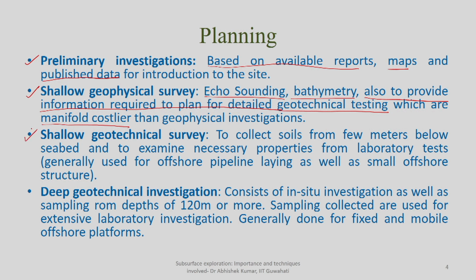Then we start with shallow geotechnical survey, depending upon the water depth and what kind of structure you are planning. So, particularly for laying of pipelines, you need not go for very detailed investigation, because of course, the load distribution of such kinds of pipeline will be limited to maybe few meter depth. So, you can go for a shallow geotechnical investigation. This consists of collecting soil sample from few meters below the seabed, because that will be the medium which will be acting as a